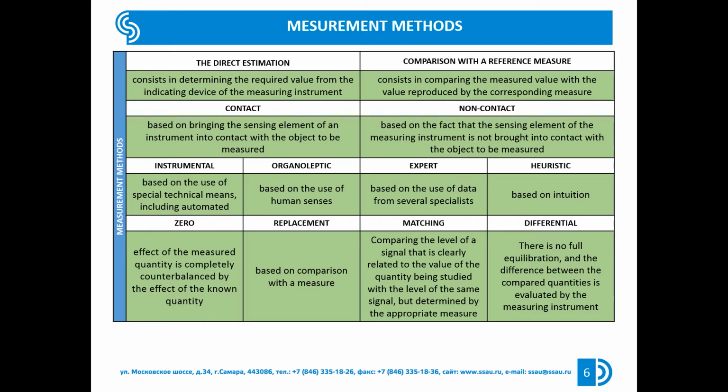The evaluation of the condition of an object can be carried out by element and complex measurements. The element-by-element method is characterized by measuring each parameter of the product individually. For example, eccentricity, ovality, cut of a cylindrical shaft. The complex method is characterized by measuring a total quality factor which is influenced by the individual components.